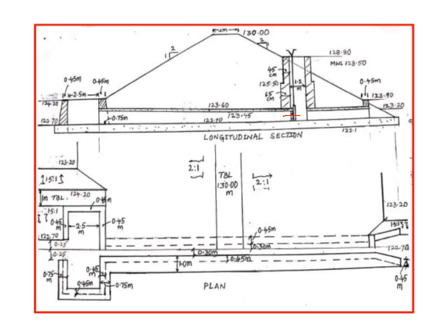Generally, the width of the cistern is 2.5 meters. The length will be decided as in the drawing. So this length automatically gets fixed. Now we have provided canal width as 0.5 meters. We are given slope of the canal as 1.5 is to 1. So here the canal bed is at 122.7. So here the water depth that we have fixed is 0.5 meters. I have given another 1.5 meters as the freeboard. So 1 meter is the difference.